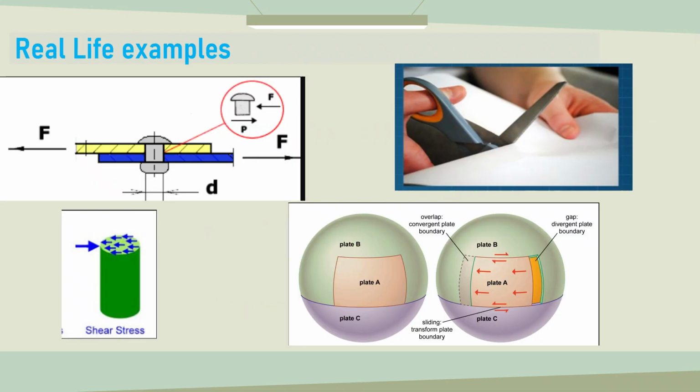Shear stress occurs in many real-life and engineering applications, such as connecting bolts that are in shear when the shear force is applied, and tearing paper, where the paper between the blades is subjected to extreme shear stress. Because the area of the paper edge is so small, the stress, F over A, becomes high enough to fail the material instantly. And aircraft structural members, like when two fuselage skins slide in opposite directions, the bolt body experiences shear stress across its cross-section.